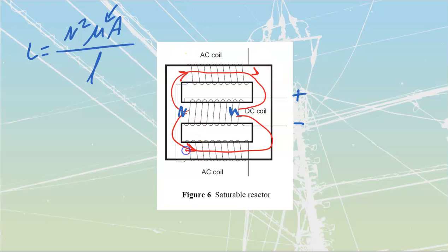Those magnetic lines are going to lock down the magnetic domains inside of my ferromagnetic material, which means that I'm going to lose permeability inside of here because I've got domains locked down. I've got lines of flux that are already blocking up some of the space. It's no different than anything else that you might have space for, whether it's freeways or hallways. If a bunch of the lanes are blocked up, you've got less room to maneuver.